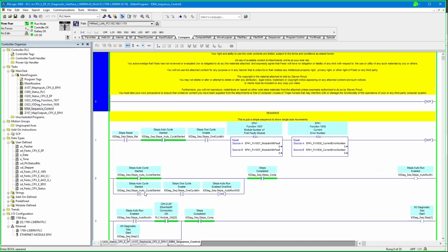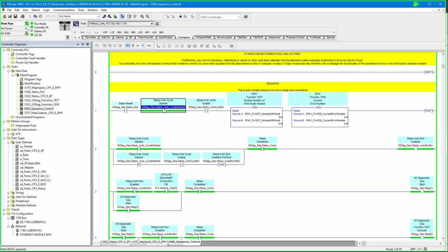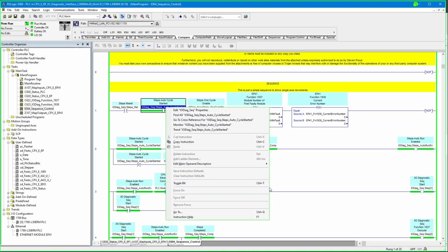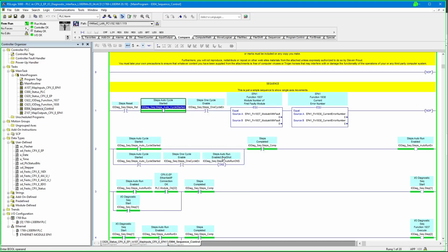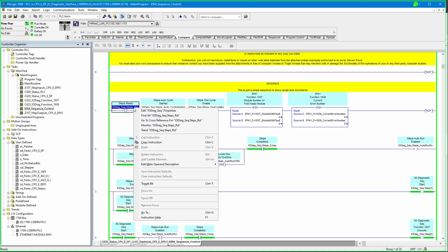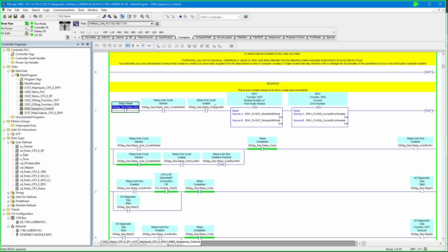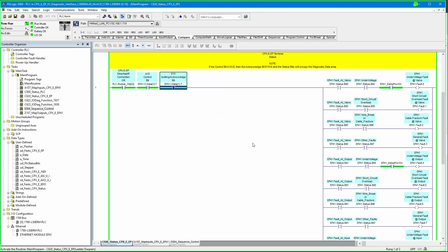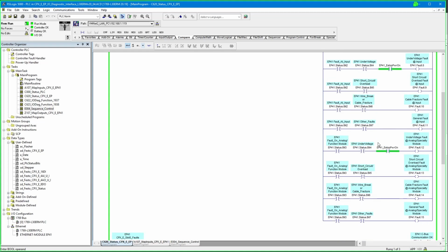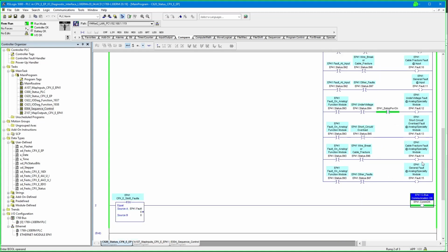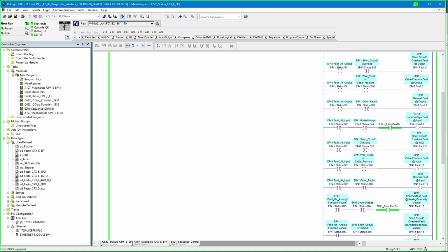So I'm going to toggle this bit, which is Control T. If I toggle this bit, it resets the whole stepper. So it's been reset. So now under the status area here, the control bit and acknowledge are both turned off, and the status bits are active right now. Okay, we don't have any faults, comms are okay.